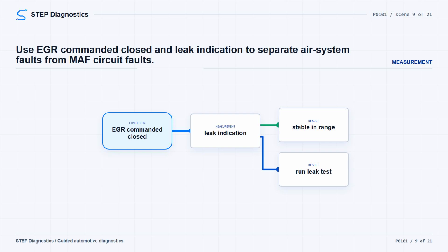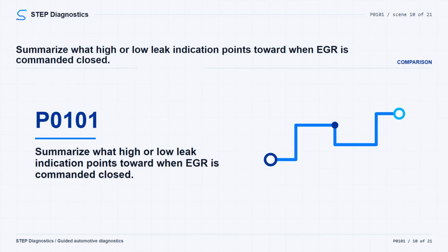As a diagnostic aid, a value greater than 1.20 to 1, with EGR commanded closed, may point toward a leak after the turbocharger, an inaccurate MAP sensor, an inaccurate IAT sensor 3, or a skewed MAF sensor. A value less than 0.80 to 1 may point toward a leak before the turbocharger, inaccurate MAP or IAT data, a skewed MAF sensor, EGR leakage when commanded closed, or PCV system leakage.